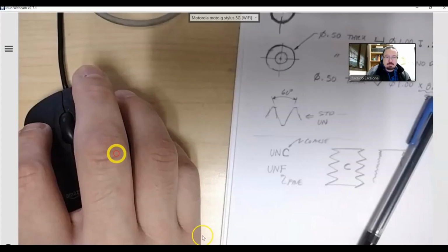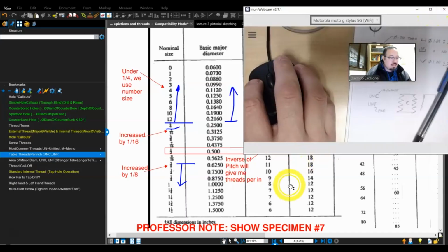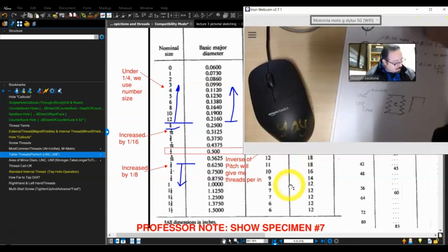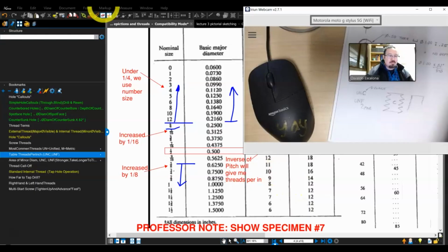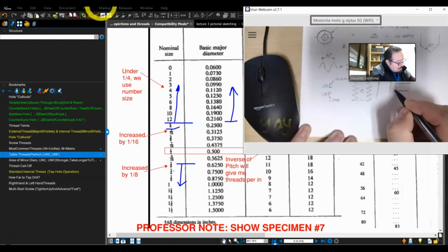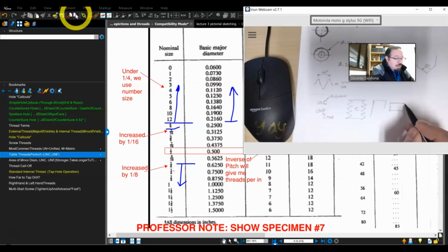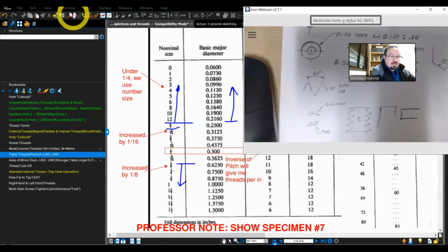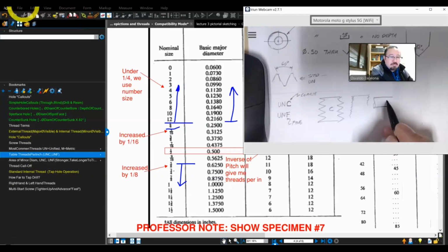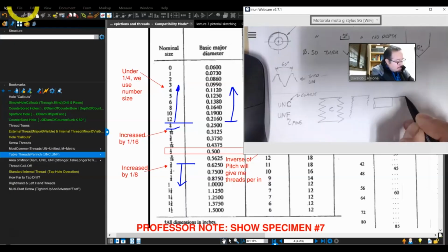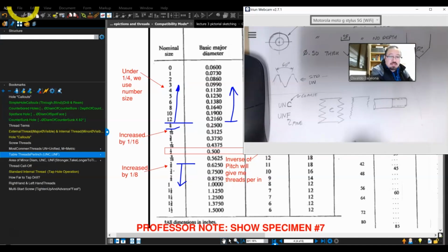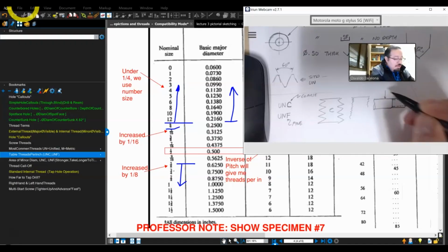So, for example, let's say that I want to cut a bolt. Well, first, I look at the size of the bolt. Let's say this is my shank, and I hope you can see this if I zoom in a little bit. This is my shank, right? And on my shank, I will have a thread. Again, this is the simplified thread representation. With your calipers, you can measure the shank. The shank will usually be pretty close to the thread.